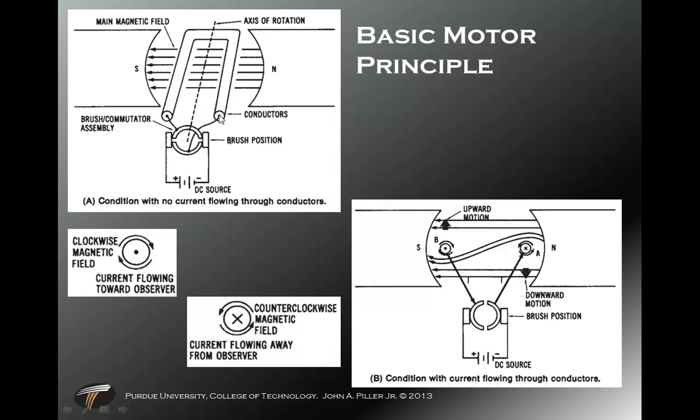So here on this other perspective, current is going this way and then around out this way. Plus to minus. This particular drawing is using the physics current flow, not the electrical design of conventional current flow. Here, current is flowing because the brush is fully touching on a single slip ring. Here, current isn't flowing because you have plus minus going across the brush, and so that's supposed to have lower resistance than the current along the rotor.